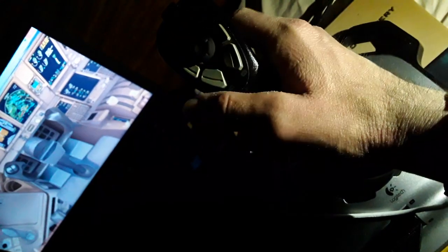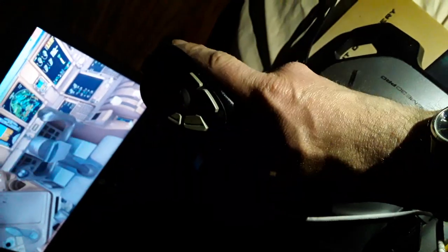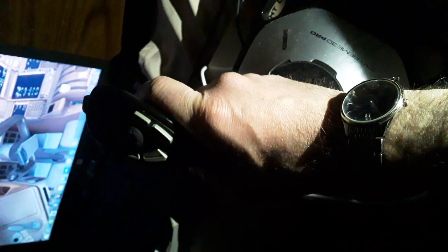Also the other side here is moving alongside with that. So we have them interconnected between the left and the right, and also control the ailerons and the spoilers. We can make bank roll, the vertical stabilizer, the rudder. So this is the general management of the side stick and the flight control system of the aircraft. You can have directional control in flight after you have effective lift from the wings and forward thrust from the engine.